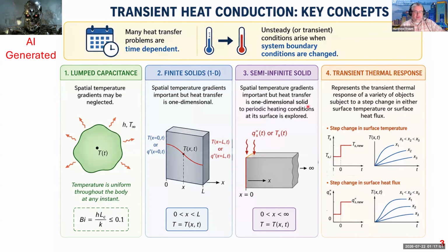And then there's this unique class of objects called semi-infinite solids. They're characterized by this impossible feature of being infinitely long. But, as we saw with fins, you can have an object that is modelable as being infinitely long, but it doesn't have to be infinitely long. It just reaches a certain point where the heat transfer doesn't matter anymore because it's reached some sort of constant temperature or temperature parity with the environment. And so we'll talk about those later on.